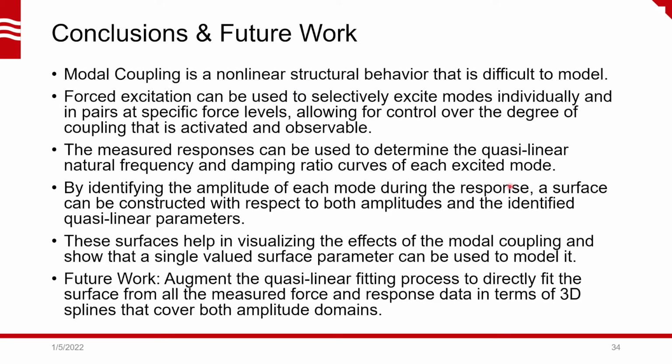So yeah, modal coupling is a very nonlinear structural behavior that's typically very difficult to model. Forced excitation, in the form of sine beats, can be used to selectively excite modes individually or in pairs at specific relative force levels, allowing you to control the degree of coupling that is activated and observable. And then the measured response from the forced experiments can be used to determine quasilinear natural frequency and damping ratio curves for each of the excited modes.